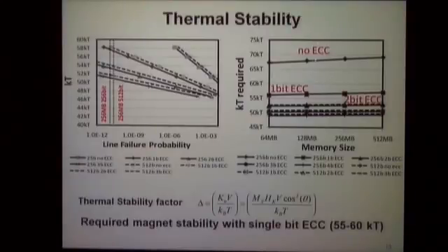Oh, the bit error rate? So the way this works in this particular case, the way it is constructed is, you start with a yield number. So you have a wafer, you have so many dies, we start with a yield. From that yield number, we can project what needs to be the line failure probability for us to meet that yield requirement. That's what is shown here.